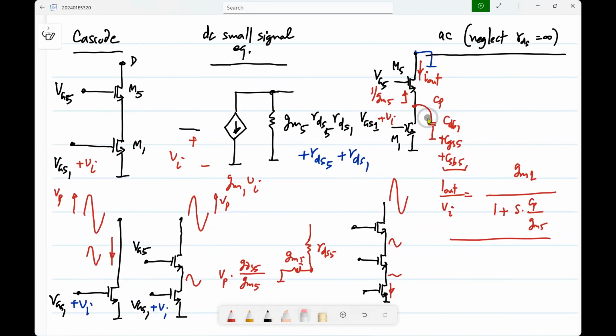We'll also see that noise and mismatch of M5 do not predominantly come out to the output, whereas that of M1 do. So for matching, if you are making a cascode current mirror, you may make M1 large, but not necessarily M5. It doesn't really contribute to mismatch anyway. So there are many cases where it has a different size, and usually smaller.